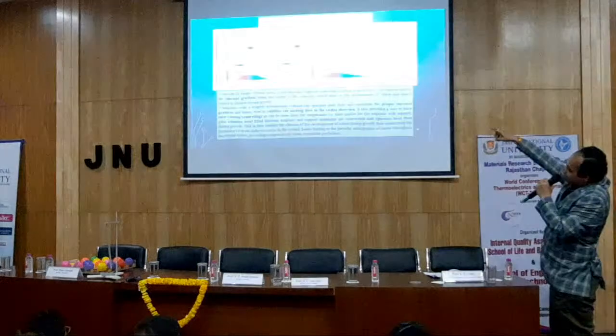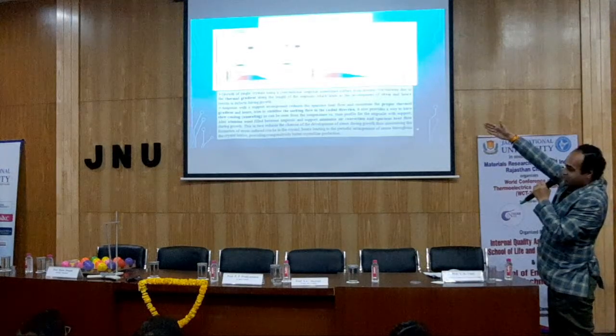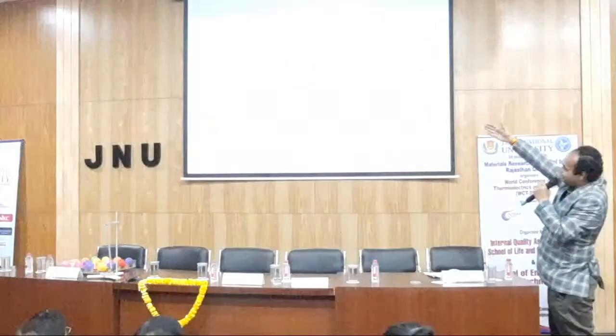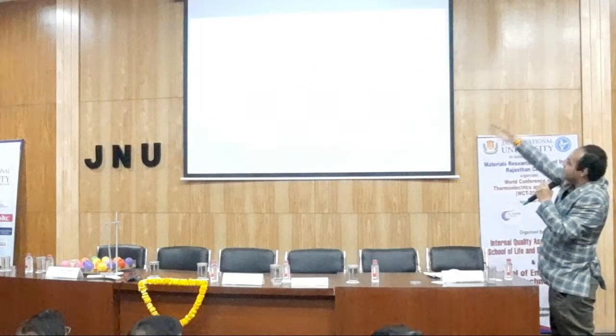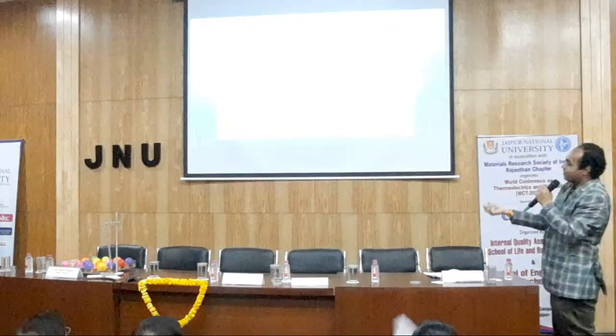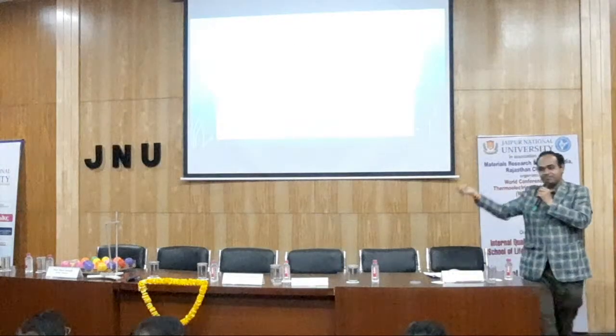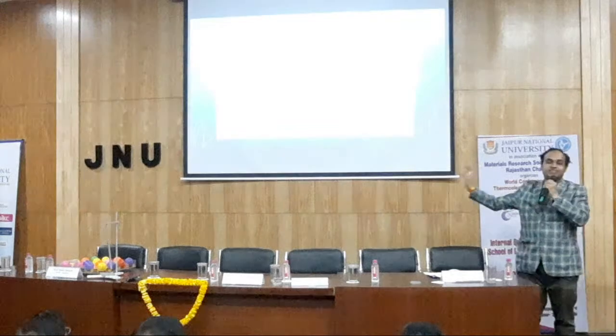The normal technique is the Bridgman technique. This is a vertical Bridgman technique. Here the crystal growth takes place by ampule lowering from the top hot zone to the cold zone. Nucleation begins at the tip and the crystal grows.